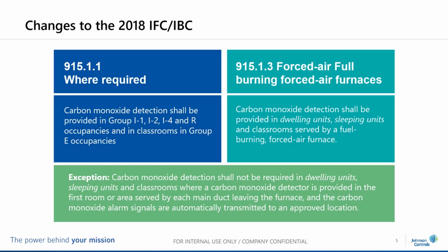But a CO detector will send an alarm signal back to the fire alarm control unit and then in turn to a supervising station, notification appliances, etc. So for the 2018 code, only CO detectors are allowed in locations outside of dwelling units. And this is where I say you really need to understand the terminology as we're going forward, on how they're talking about detectors as opposed to alarms. They're not the same.